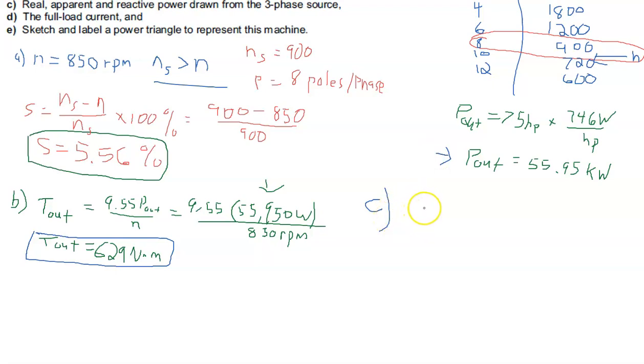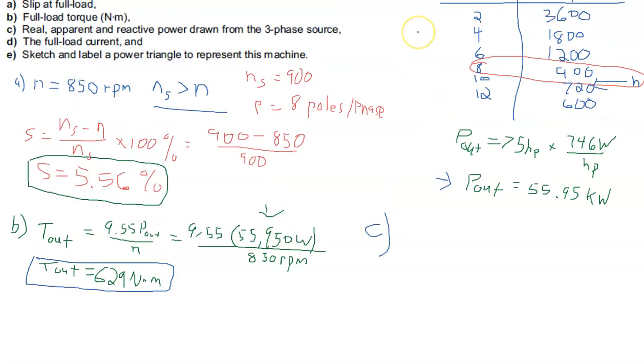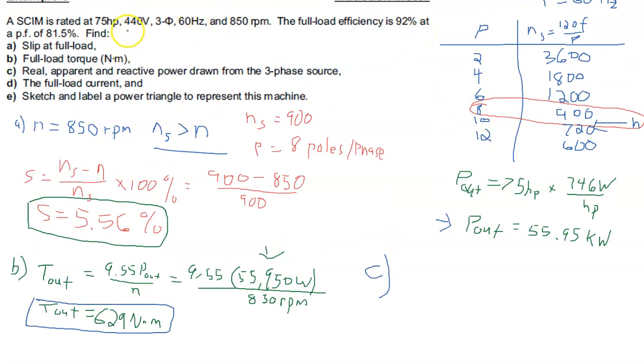Think about our equations and the information we've been given. We've been given the rated voltage of the machine. If I scroll back up there for a second. But we don't have any current. In actual fact, we're asked to calculate the current. And so we can't calculate S three-phase as our beginning point.